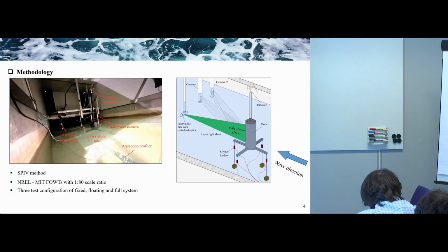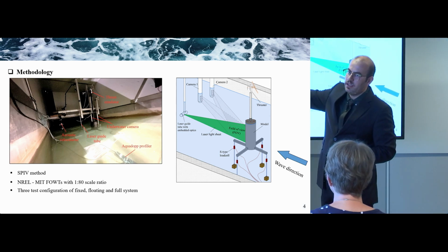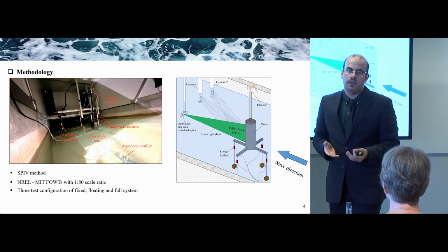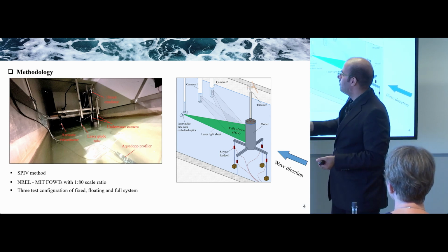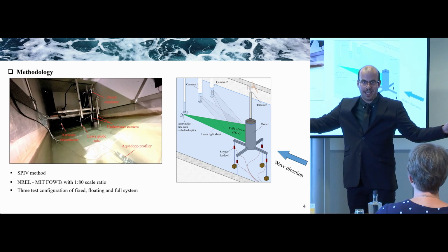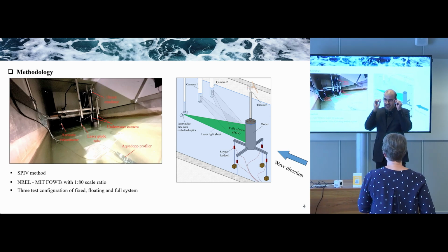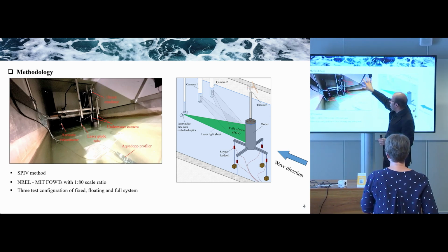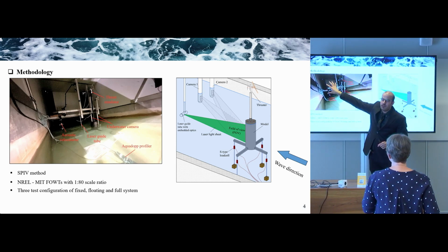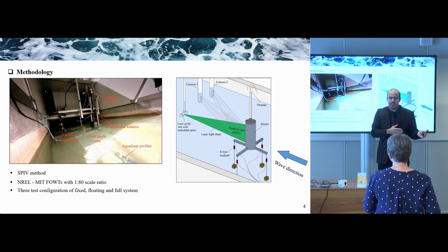The problem that we have here is about the health and safety requirements. We had a really wide and large tank hall area, so we couldn't use the laser with naked eyes. What we did was to put a laser safety cover over the area of the measurement, so that the laser would not make somebody blind.